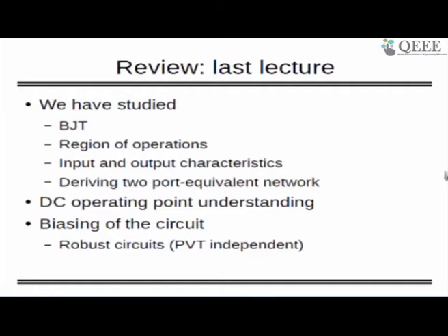But if your base width is not ideal, and it is actually smaller, then you will see some slope in the active region, and that slope gives you 1 by R0. R0 is decided by the base width modulation, and this whole effect is known as the early effect.